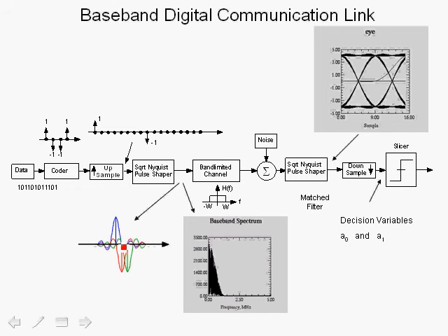Each impulse response is the symbol for a Nyquist raised cosine pulse, which, as we have indicated before, has 0 crossings at equal intervals. So at the sampling points shown here, we have 0 intersymbol interference from the pulses. That is a nice property of the raised cosine filters. The spectrum at this point is band limited.